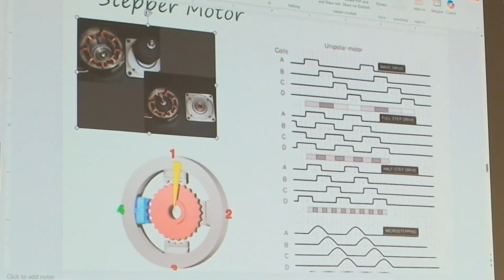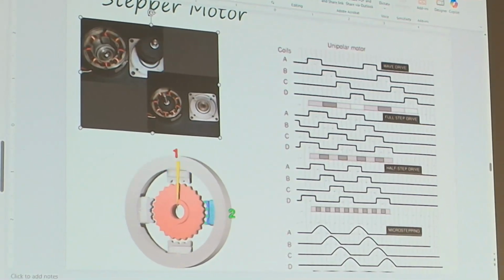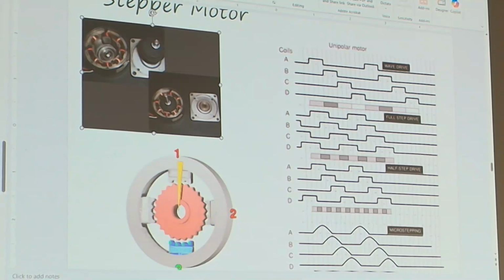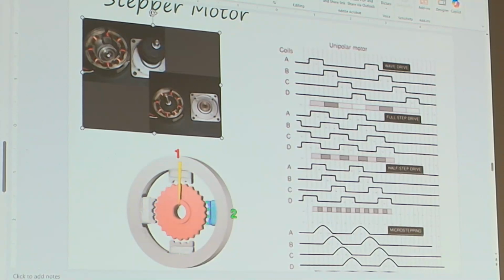Now, when I was a kid, we made our own drivers. No, we actually did. I made my own stepper drivers using some flip-flops to create the waveforms of when things turn on and off, driving it with a clock signal in a direction. It's a simple state machine. It's not that hard. It's a good exercise. If I teach digital logic, that usually shows up as a problem.